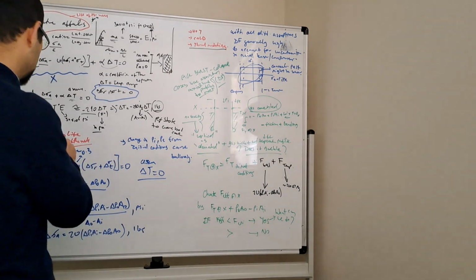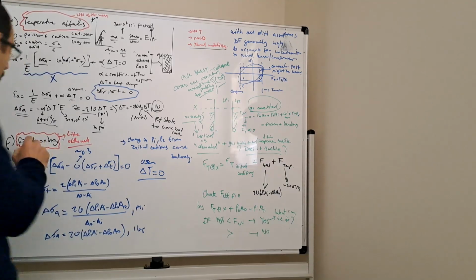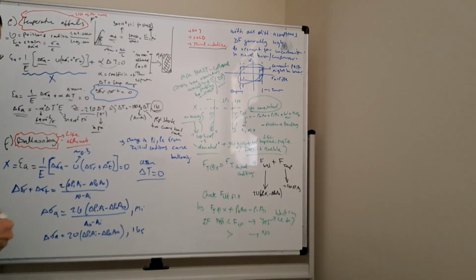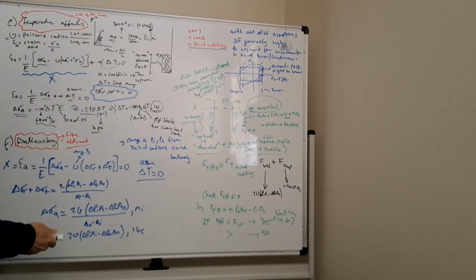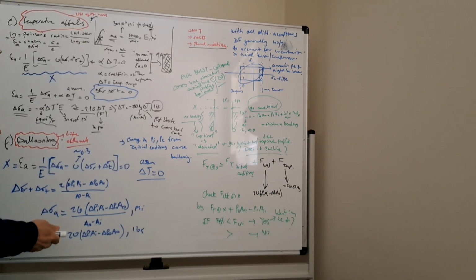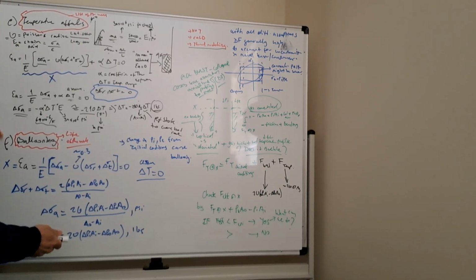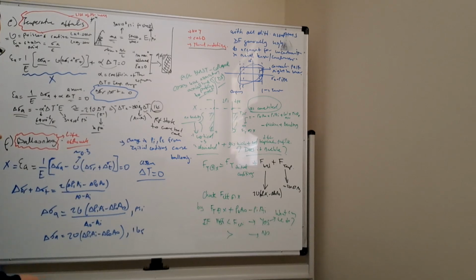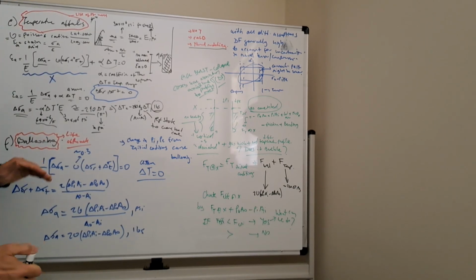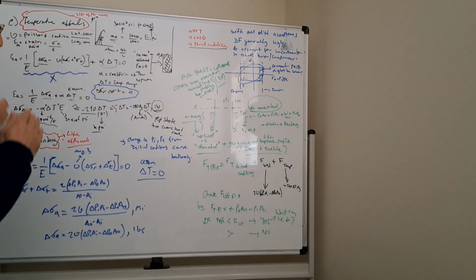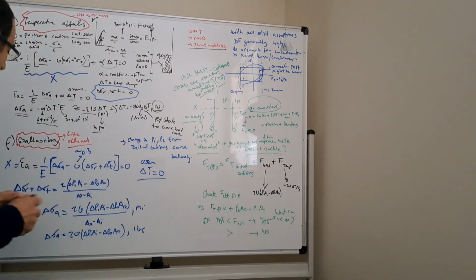All right, so the next one that I'm going to talk about is the ballooning. This is one of the most significant elements. One of them is temperature, and one of them is ballooning, basically the change in tension profile from the post-cemented case or locked-in tension.